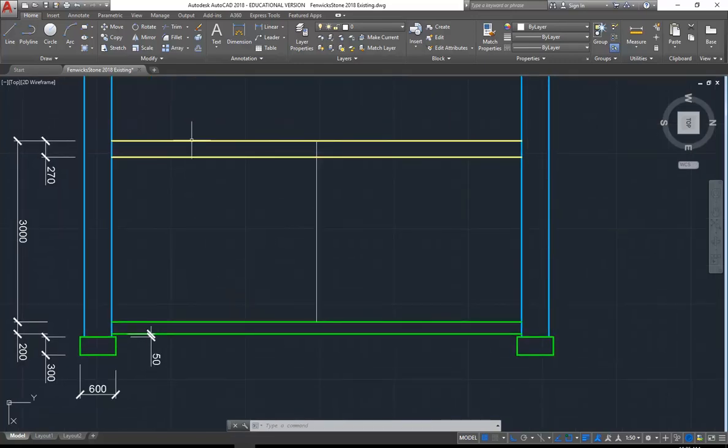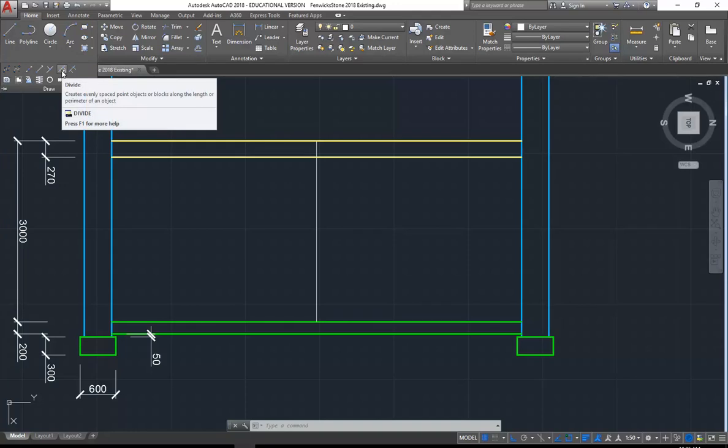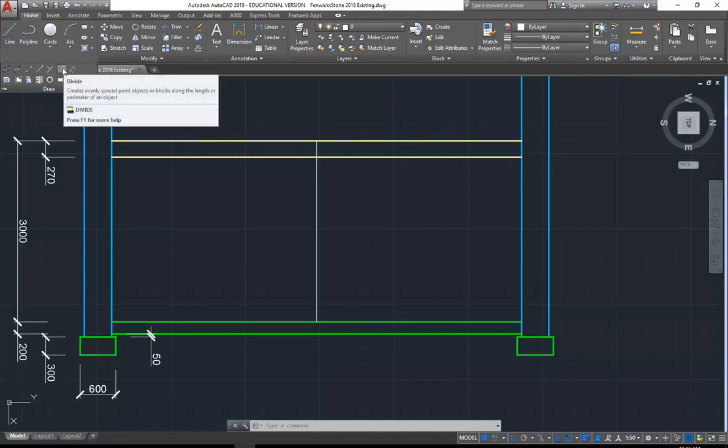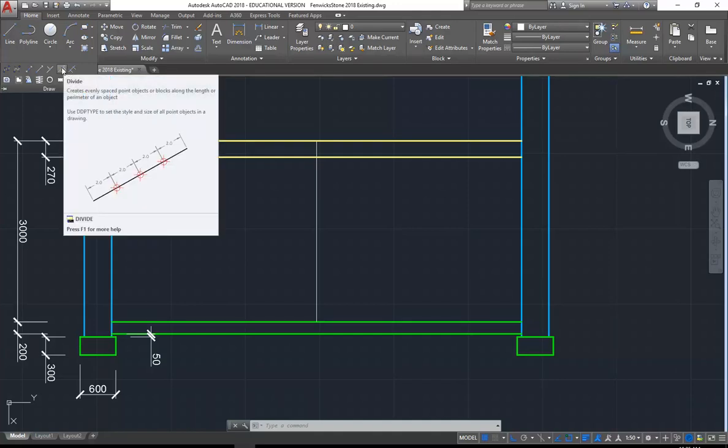And then comes the excellent command in AutoCAD you have for dividing things, called divide. So I'm just trying to see where the button is. I use the shortcut most of the time. So it's not under modify, it's under draw, isn't it? Yeah, so there it is. You can click on the panel where it says draw, and then you'll see there's an icon with a line with an N. That's the divide tool. And you've all used it when you did the geometry exercise.